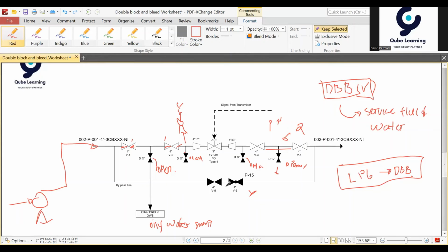So first we have to open these two valves to ensure that the discharge is cracked open, and then if the flow of the pump goes high and the flow increases, maybe right here is the key operating flow of the pump, and then you can also open this valve, and then you have to close this valve.